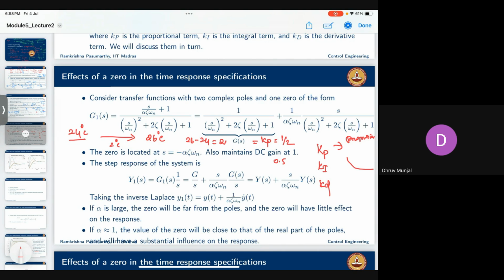This is the disadvantage of the proportional controller. So there comes the integral controller. If I include the integral and the proportional controller, what this integral controller will do is it will try to save this value, initially 2 degrees Celsius. Then the difference between these will be some degrees Celsius. After that, I would introduce some proportional action, so that maybe there is a 7 degrees Celsius difference. So this will keep track of it and add again. That depends on the difference of this error. So this will help us reduce the steady state error, but it may increase the overshoot.